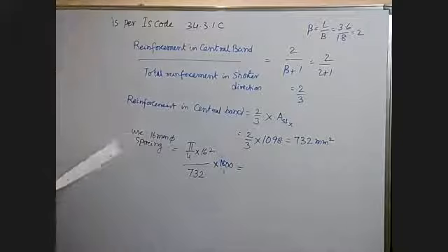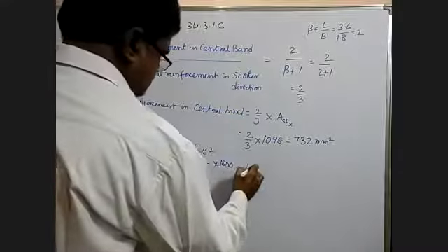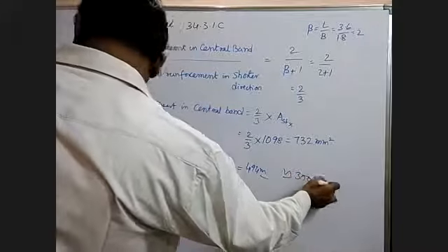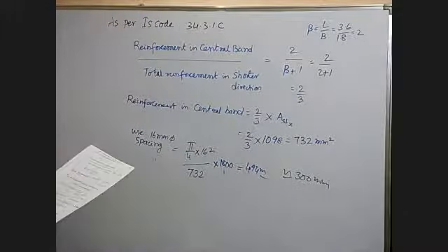It comes to 494. The maximum spacing is 300 only. So restrict this to 300 spacing.